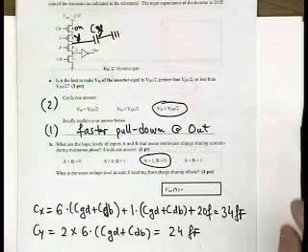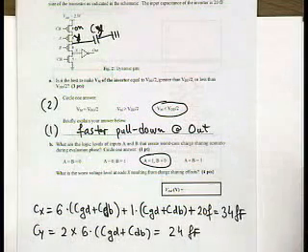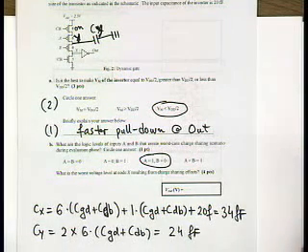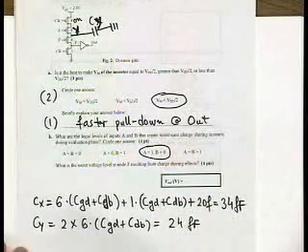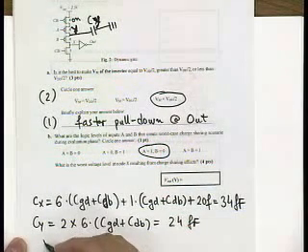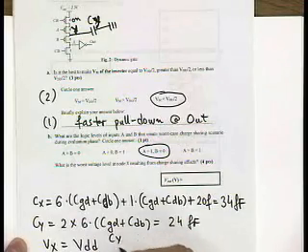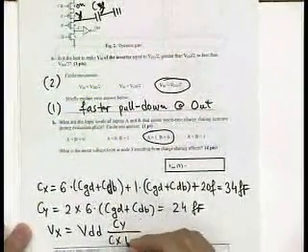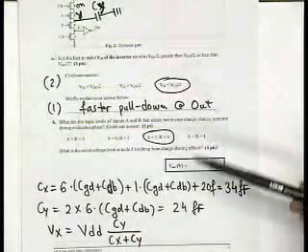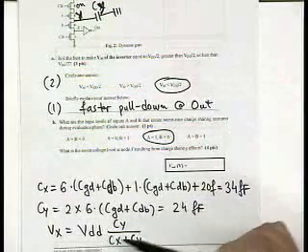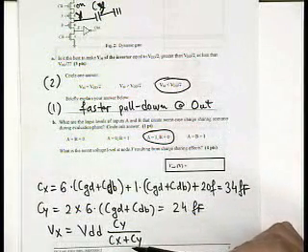Now you notice that there is no Miller effect in this case, because this is now static conditions, right? It's been a long time that your inputs have settled, and now what you're looking into is the value of your voltage in the charge sharing mode. And so now you have that your Vx is equal to simply VDD times Cy divided by Cx plus Cy. And since we didn't give you threshold voltage and mentioned that you should really consider this case where you assume that delta V is greater than Vt.